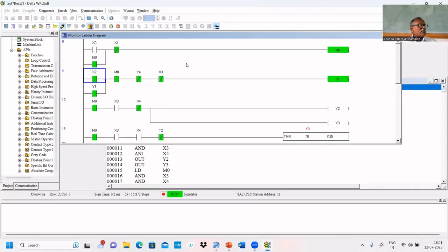It means the inlet valve is open. After some time, what will happen to the bottom proximity switch? It becomes 0 because the level will rise above that proximity switch. That's why it is not empty. Am I correct or not? That way we have to simulate.